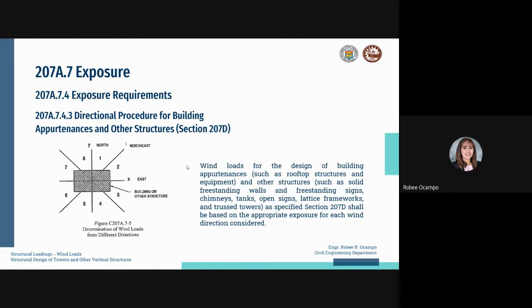So basically, your wind load will be more than one case. If you have 8 parts, the generic number of cases for your wind load will be 8. It could even be more than 8, but generally you have 8. Now your load combination, for example load combination 4 for strength design, includes the wind load.